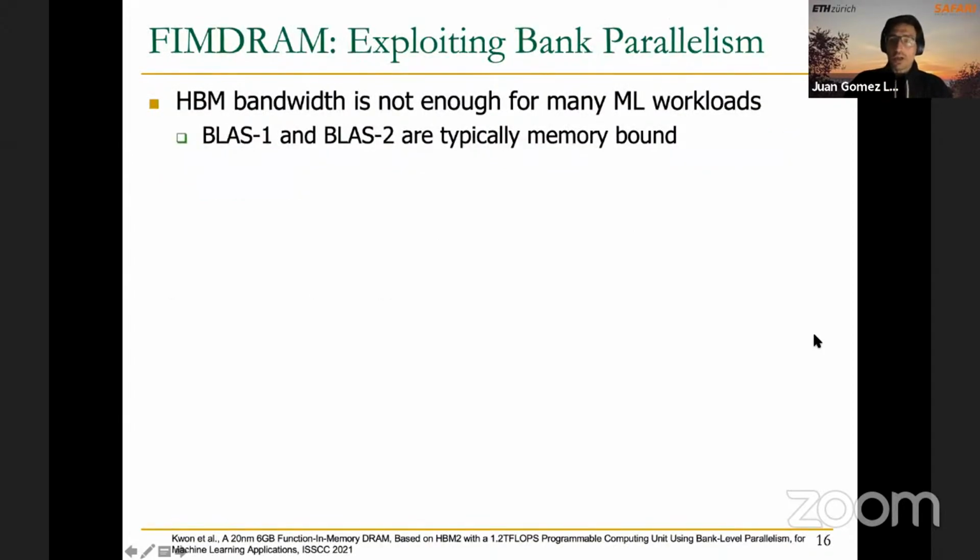Okay, so after reviewing HBM, let's start talking a little bit more about the FIM DRAM architecture. HBM bandwidth is not enough for many ML workloads. And this is something that we can observe in our daily work with GPUs, for example. Many workloads, even though they are already using HBM memory, are still memory-bound.